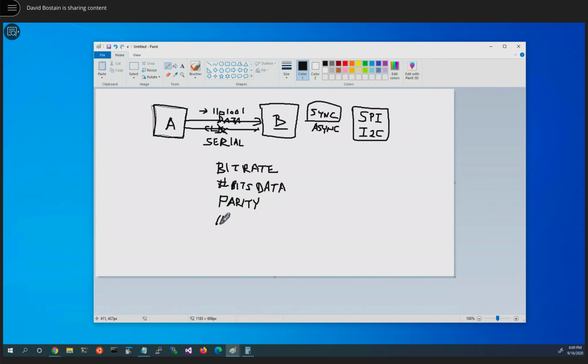And finally, we need to know the number of stop bits. At the end of the transmission of a character, we're going to put in some stop bits to say you've seen all the characters and possibly the parity, but I don't want to start sending anything else yet. This will force me to cause a little bit of delay to occur, so you may process the message before any other thing can happen. This will normally be either 1 or 2. Won't be long, but it'll be an amount of time when you can process the data that I am sending.